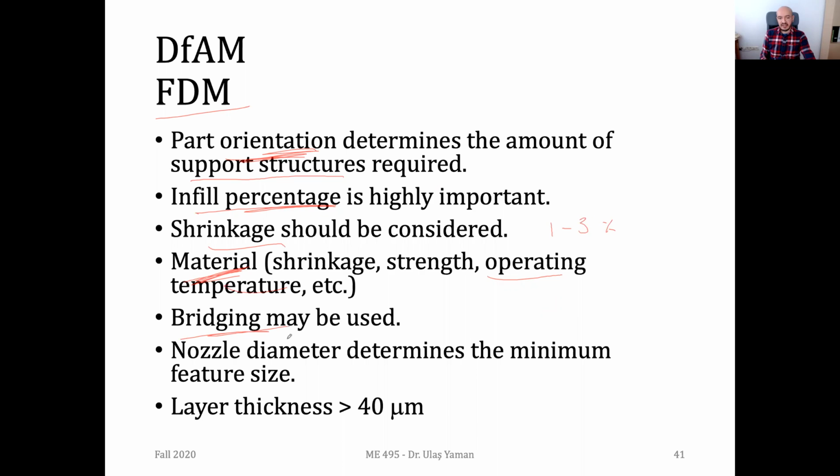Another thing, bridging might be a nice idea. If you remember the letter H, if this length is not too much, then without having support structure, you may pass this part in a faster manner, and you may turn your fans fully on in this region so that it will be solidified and cooled quickly, and you don't need to have support structure. So that might be used in some designs, but the thing is that you need to keep this distance